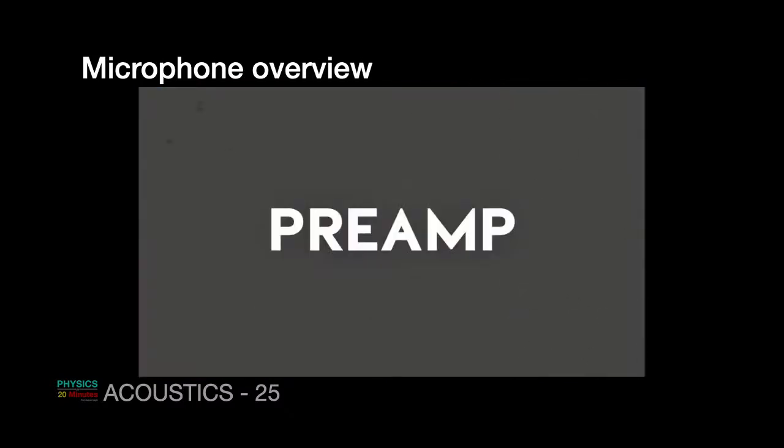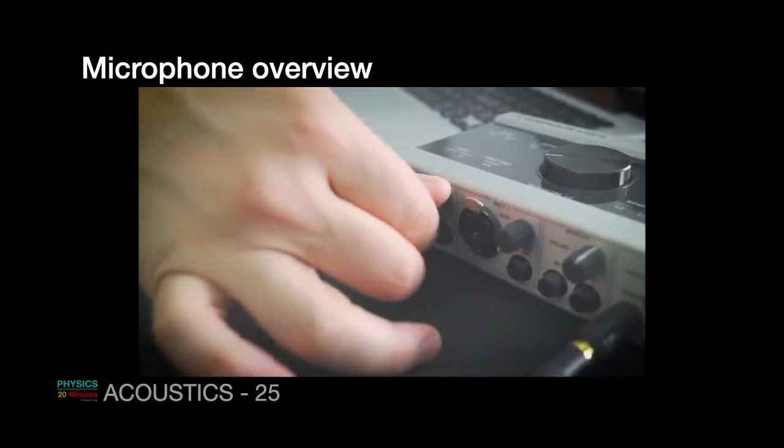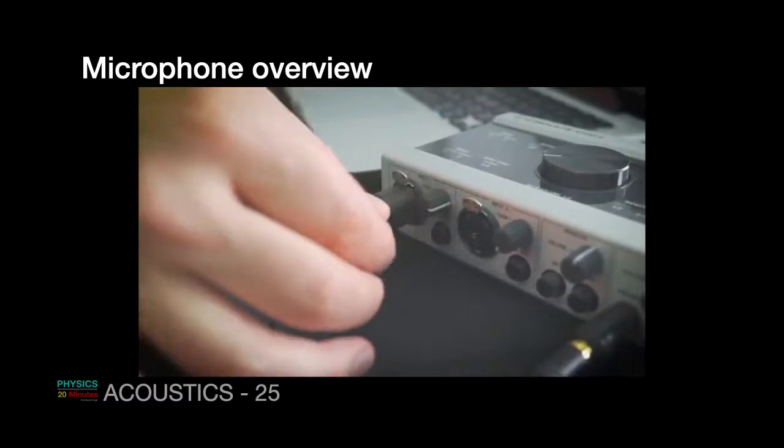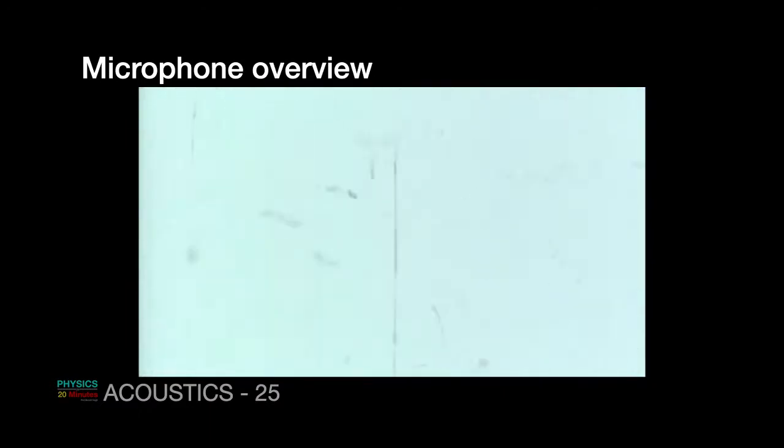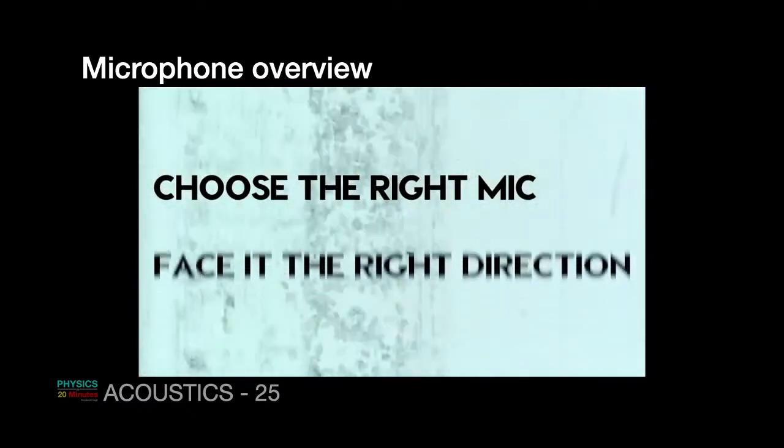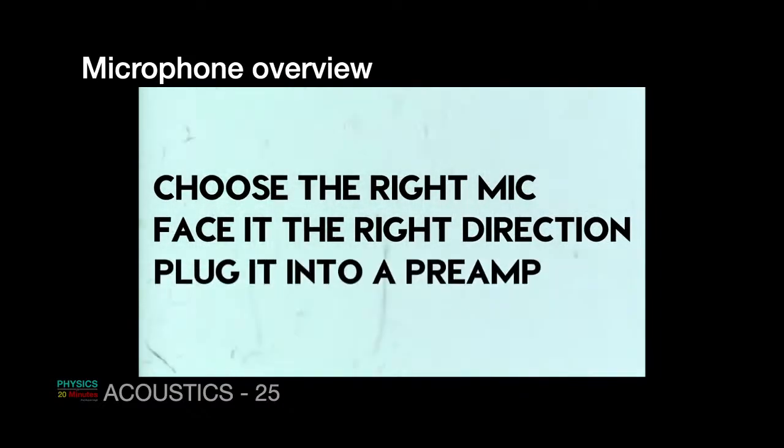Microphones create a very weak signal, so you need what's called a preamp. Your audio interface likely has at least one of them. These will amplify the very low-level electrical signal to a useful level, and it makes it possible for your audio interface to sample the fluctuating voltages more accurately. So there you go. Choose the right mic, face it in the right direction, plug it into a preamp, and then you're ready to start capturing the sounds of the world all around you.